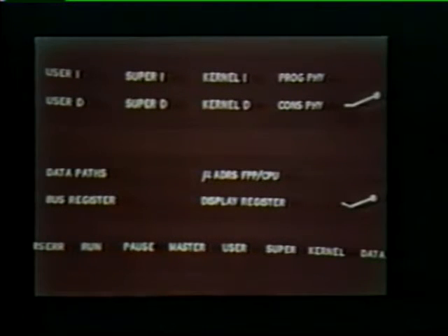Most systems have a unique set of monitor lights tailored to the individual system. Of the many monitor lights that are used on the different consoles, only the run light is present on all of them. When this run light is on, the processor is progressing through an instruction. When the light is off, the processor may be in control of the bus and waiting for a data transfer response, or it may have relinquished bus control to another device.